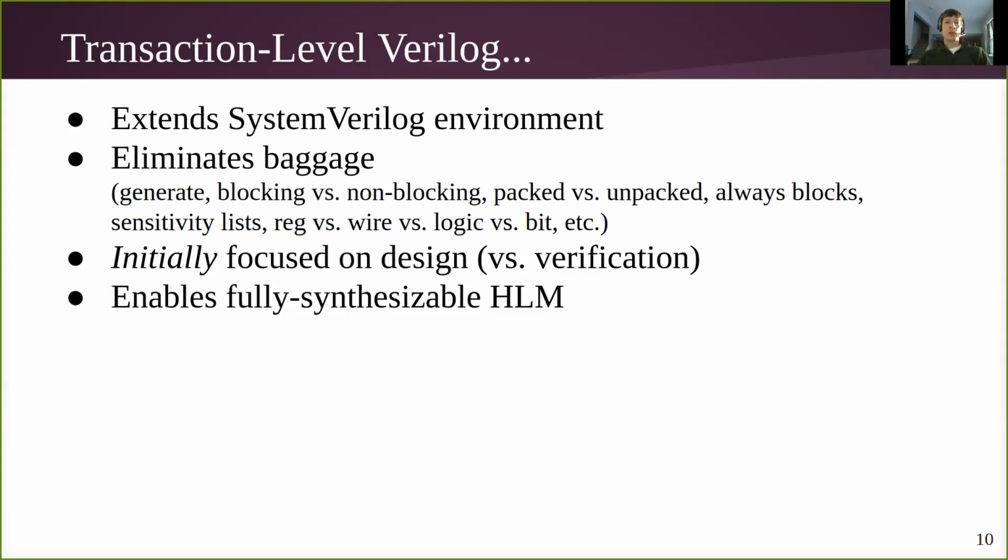So things like generate blocks and the notorious blocking versus non-blocking assignments, packed versus unpacked data types, and the various restrictions around when you can, where you can use what. Always block, sensitivity lists, reg versus wire versus logic versus bit. None of these concepts that are more sort of legacy about the modeling methodology behind Verilog are relevant any longer with transaction level Verilog.